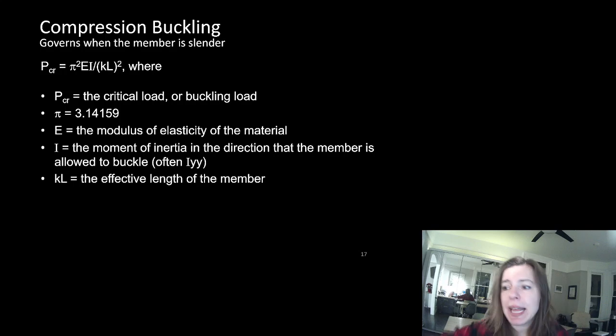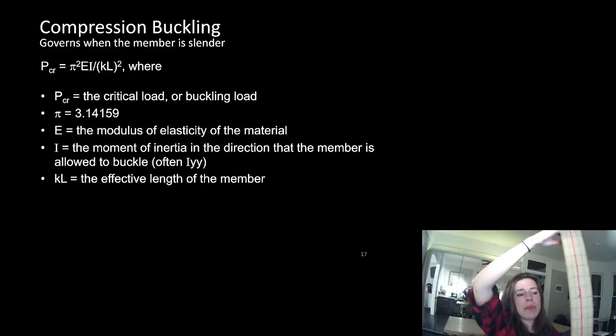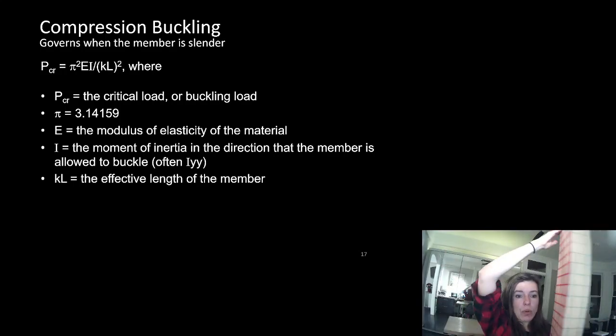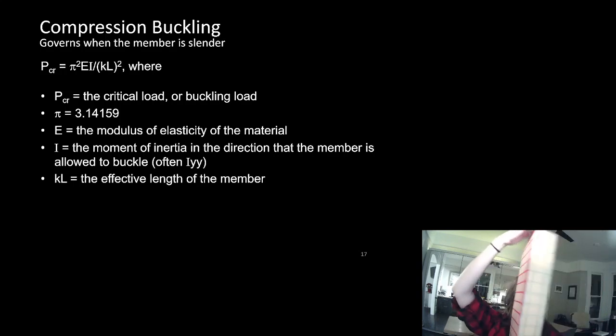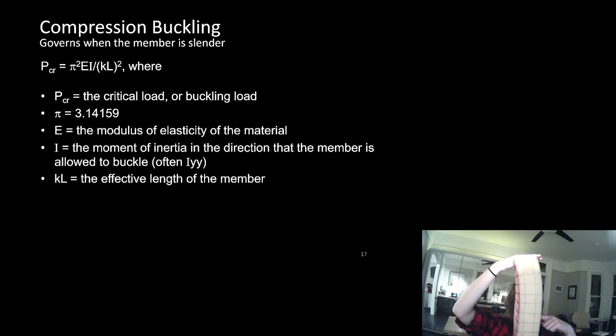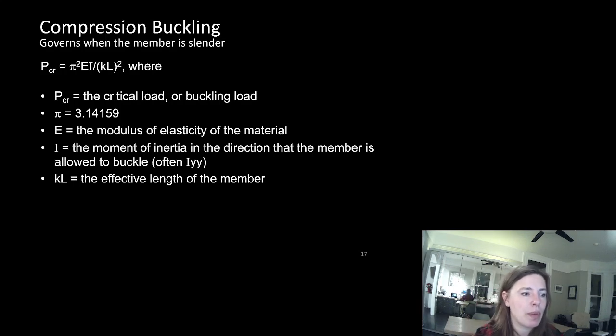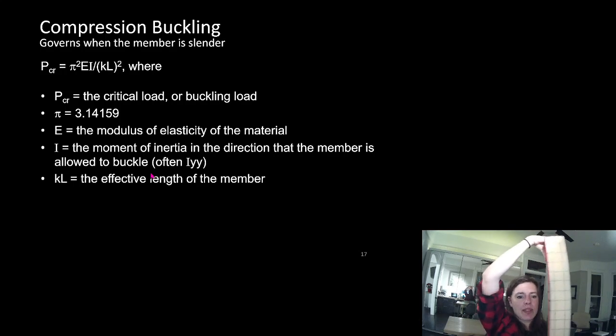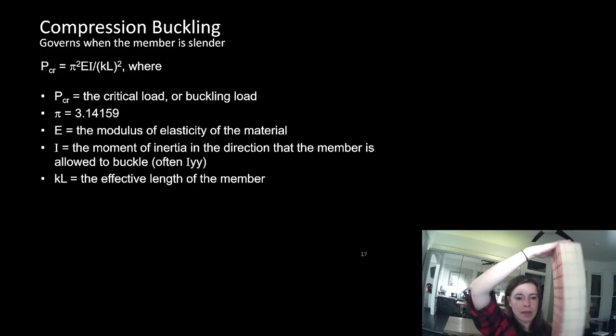There's also a second thing. That would be its effective length. Normally its effective length is its height. If I put this here, its effective length is half its height. Now, in fact, it gets even slightly more complicated than that, but don't worry about it too much. There's also a different thing that happens. Normally we're talking about pinned elements.